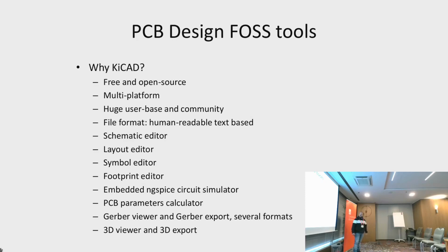It does have a very nice symbol editor and also a nice way to organize the component library. So symbol and footprints. It has an embedded ngSpice circuit simulator. So as I mentioned before, sometimes you need to simulate part of your circuit. You don't need another tool for that. You can just assign the simulation model to your components, and you run the simulation within KiCad.